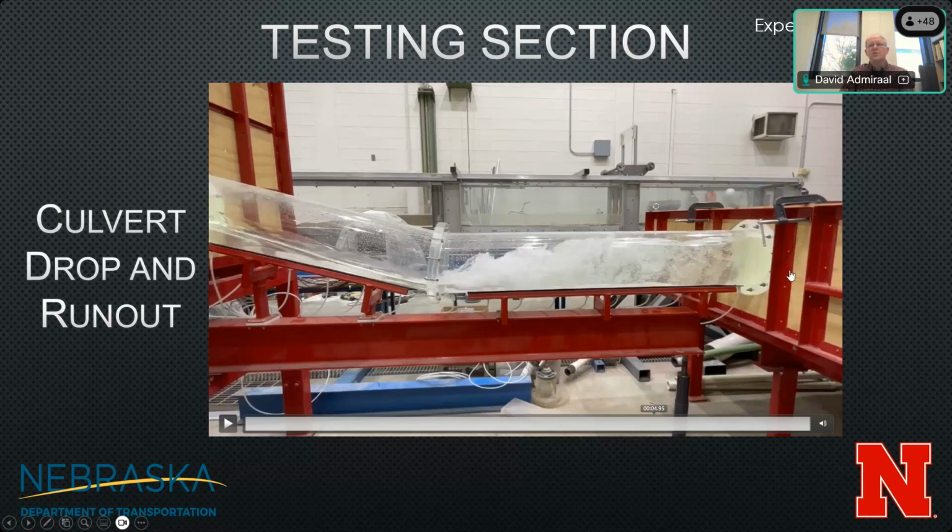Now, what you hope to have is that your dissipation structures create that hydraulic jump. The problem is when you create this hydraulic jump, you're backing up the flow. So you reduce the energy somewhat, but by backing up the flow, you create additional potential energy, which once it gets past the dissipation structures can lead to higher velocities. And that's one of the things that we saw for our higher weirs, and I'll show you that when we get to the results.